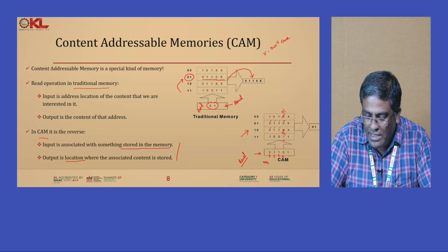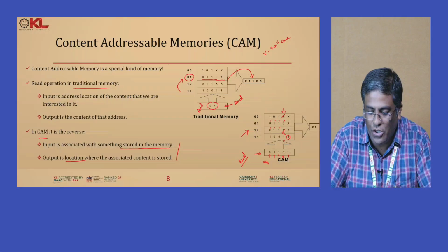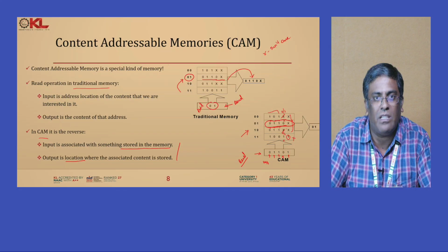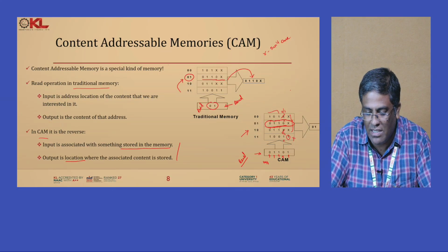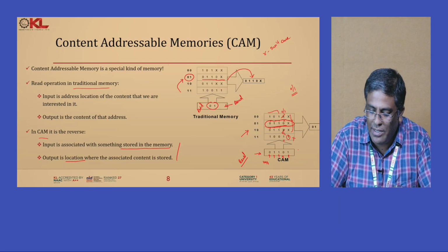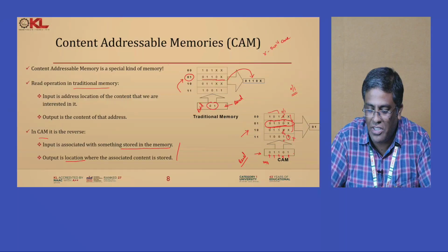Now we can see what is the next one, that is nothing but 1. Where is the 1 available? Yes, the 1 is available here, but the remaining MSBs are not matching, so this is not eligible for us. And there is a don't care condition, all three conditions are available, but the remaining MSBs are not eligible to be selected. But we can see that there is only one, that is this condition, where the remaining 4 MSBs match exactly and the last LSB has X, that can be 0 or 1, a 50-50 chance. That is going to be the maximum match we are searching for in your CAM.